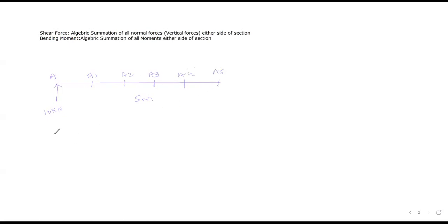Now I am considering bending moment at A1 from left. I will cut the section at point A and find the moment from the left side. To calculate simple bending moment you have to find the normal moment. Now that is the difference between moment and bending moment. We will discuss later on. Don't worry. But to calculate bending moment you have to find the moment. To get a moment, we will require a perpendicular distance. So we will get bending moment at A1 equals 10 into 1. Yes or no? I don't need the answer, I need the equation. That's the reason I don't write the answer.